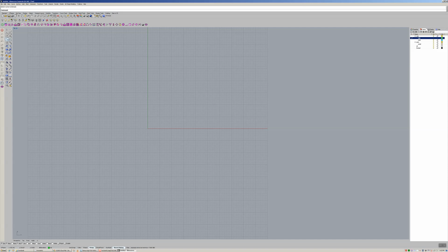So I'm going to go into this next icon over here. It's a rectangle. Okay, it's a curved rectangle. This makes just a box. All right, I'm going to left click on that. And Rhino is asking me, what do I want to do? Where's the first corner? I'm going to start from the center. So now this box is going to expand out from the center.